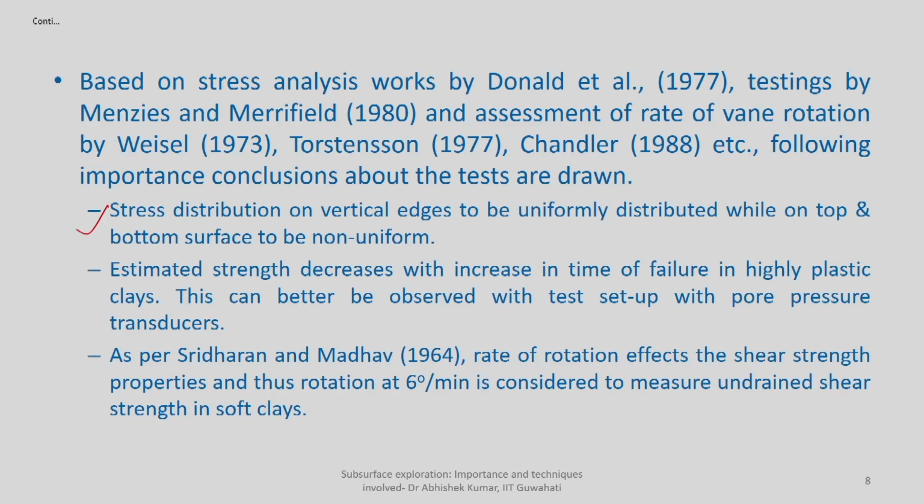Second, the estimated shear strength depends upon how much time is required for failure. The more the delay in failure, the lower the shear strength, so you will be underestimating the shear strength of the material. This can be better observed with a test setup with a pore pressure transducer. If you apply the rotation very slowly, what will happen? You will get an additional resistance based on the pore pressure, because in fully saturated soil, if you rotate very slowly, pore pressure generation will dominate, and that will induce additional resistance to rotation.